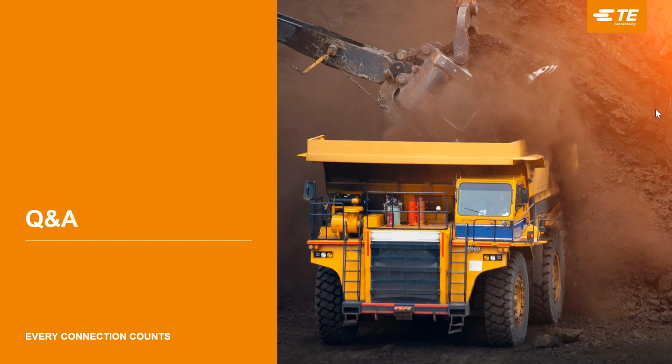And then in the case of the back of the connector where you have wire or cabling going in, there's also pre-installed seals, or seals that are installed during the cable assembly process, that provide sealing around the jacket of the cable itself and into the housing, to be able to withstand both IP67 and IP6K9K types of water ingress. So there should be no need for additional sealing or epoxying or potting of connectors.